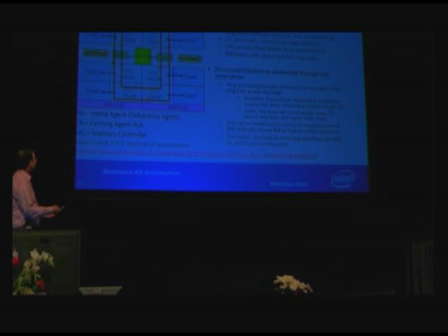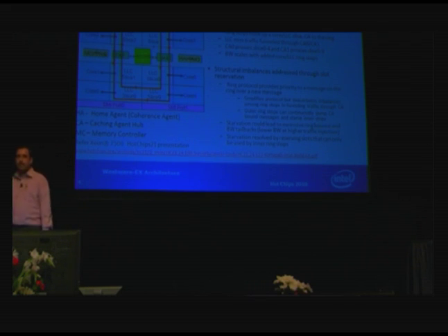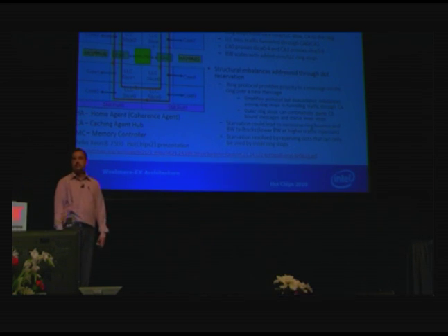So we try to minimize that. It is a bidirectional ring, and there is intelligence built into how you route. So you do take the shortest route, but there is a variation in the latency, you're right. One more related question. When something is requested from a slice further away, does the data migrate to the requester, so the next access is faster? No, we do not support any such heuristics for migration. On an address by address basis, it is cached in a fixed slice. Okay. Thank you.